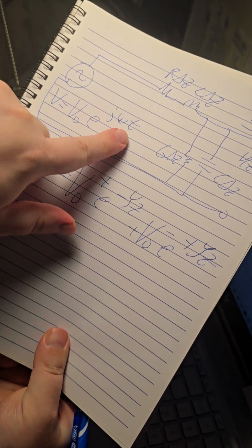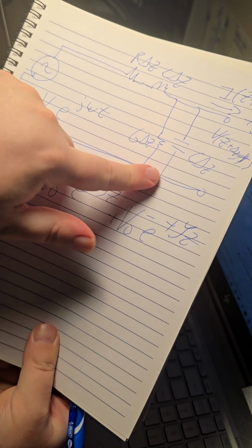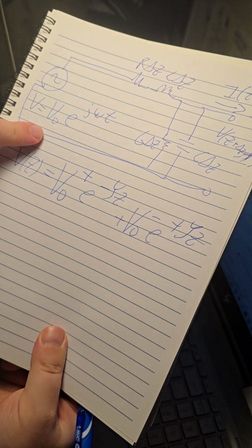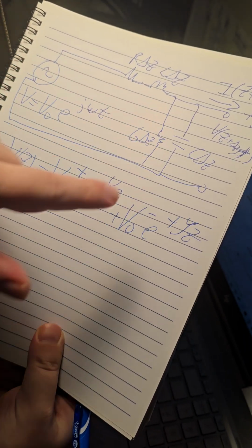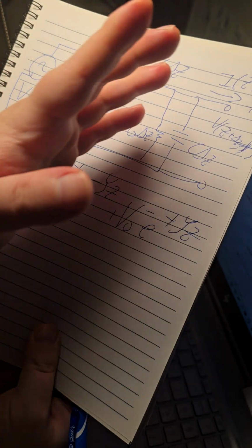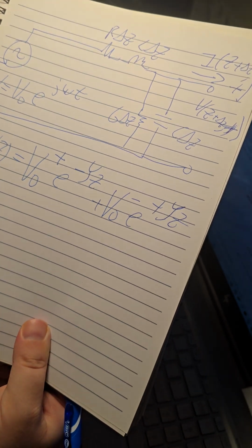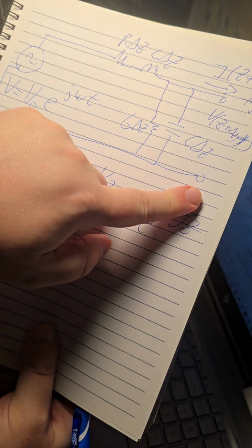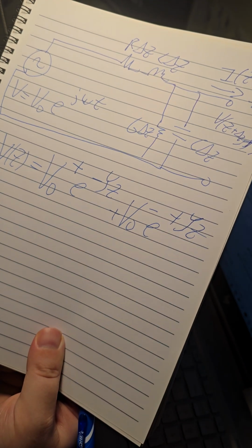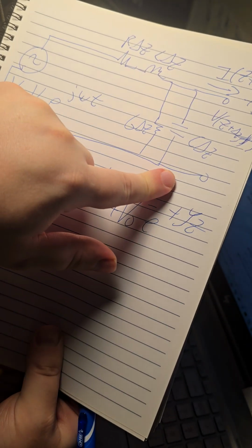Because a natural phenomenon is when this gets to our load, remember this is the ground and this is the top or dielectric, and that's the bottom plane and that's the conducting plane. When the source gets to the load, it actually bounces off of it because it never reaches it at the level it's supposed to stay at. It's a wave. So remember, when a wave hits an object, it bounces backwards. That's what happens to waves, because it's not a steady voltage anymore, it's a wave. So when a wave gets to the end, it bounces back.